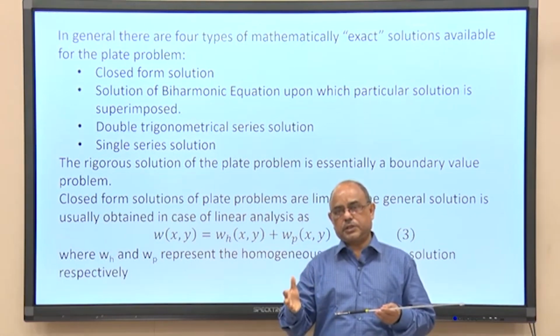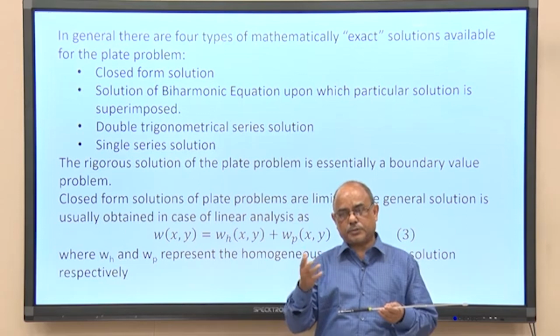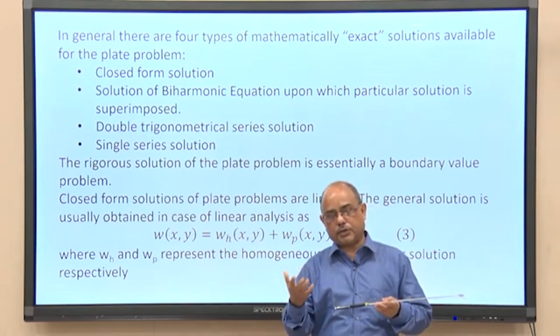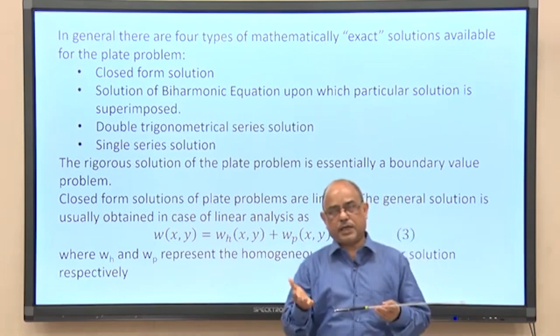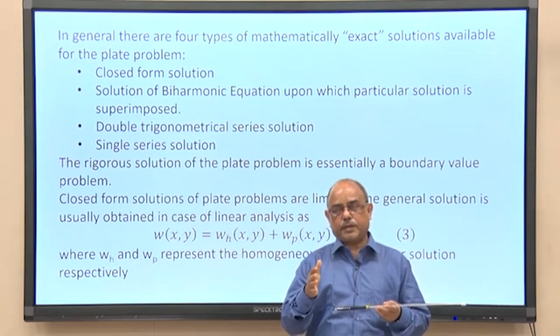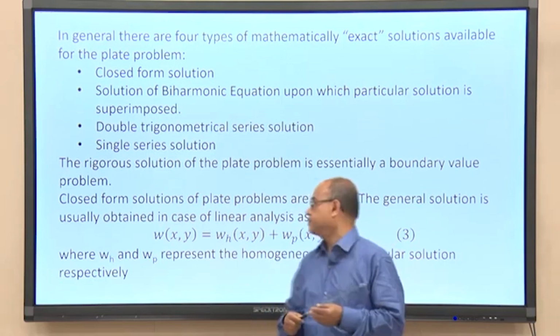So, imposing the boundary condition at the two edges, you will get the 4 constants or 4 equations that have to be solved simultaneously, and finding the constants of integration is a problem. In many cases, to simplify this, we adopt symmetric loading, antisymmetric loading. So many techniques are used to simplify the calculation of the constants of integration, because it sometimes involves a lengthy calculation.